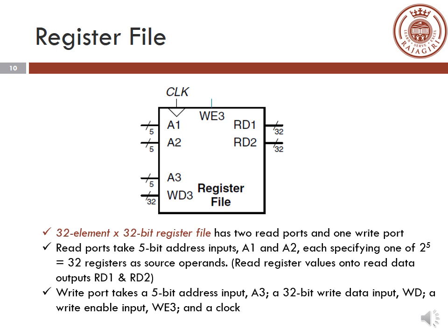That is why you have 3 ports, 2 ports associated with read and 1 port associated with write, which comes from the R-type instruction, which can take 3 different register values. That's the design criteria which has to be understood.